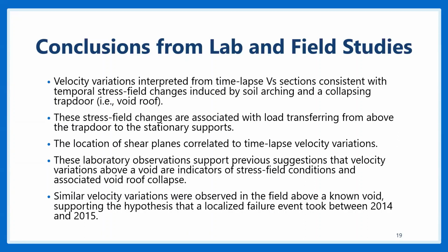And based on these laboratory observations, we believe that we can indeed use shear wave velocity as an indicator of stress related to the collapse or failure of a void structure. This topic has been discussed in the literature, but, to the best of my knowledge, it has not been shown or exemplified in any sort of laboratory experiment in real time.